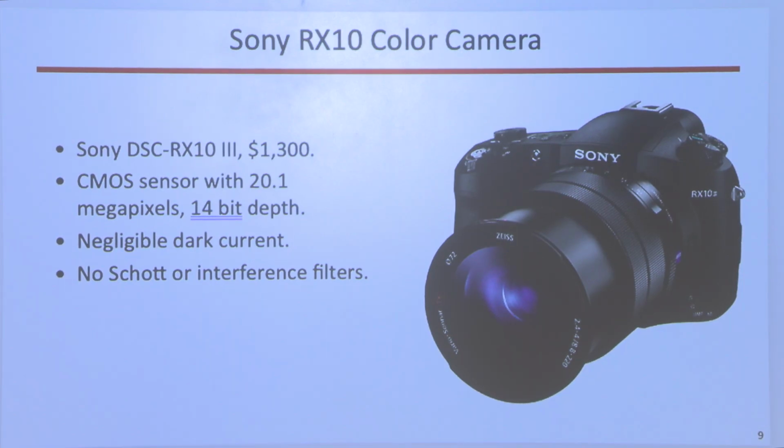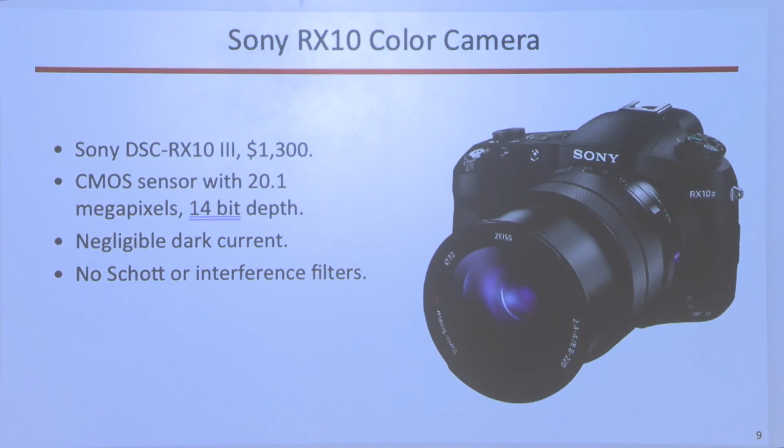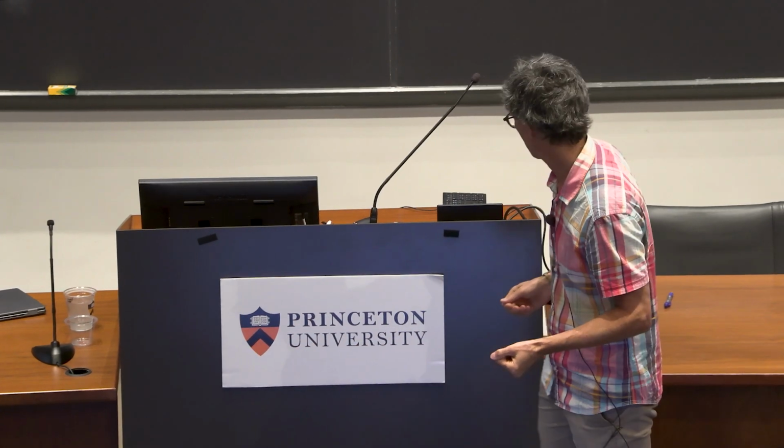But this type of thing usually is slow and won't work well for fires. It takes you a second or two to switch the filters, and in that time, your fire can change. And so we decided not to use any external filters. You could be smart and use 2 cameras, both with filters on them, and trigger them at the same time, but they'll always be looking at slightly different things, and then merging these images together to do ratio pyrometry gets very difficult.